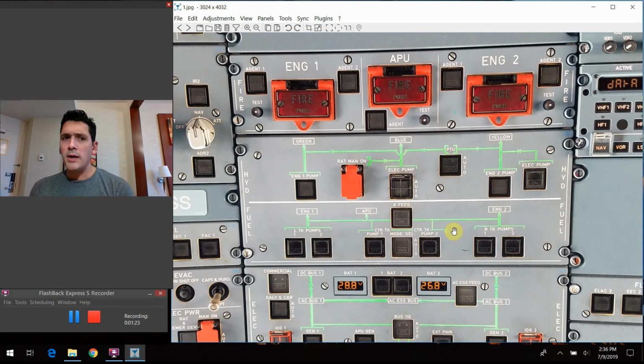And the other way I think about this hydraulic system too is it's also like an unlimited means of bending and piping various control capabilities through the inner workings of the airplane. I mean, imagine if you had to snake wires and pulleys and cables and all this kind of stuff through all these bends and turns of the structure of the airplane that you would need to route from where the control input is made in the cockpit maybe out to the surface.